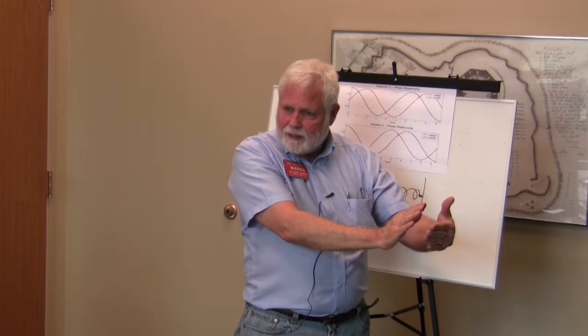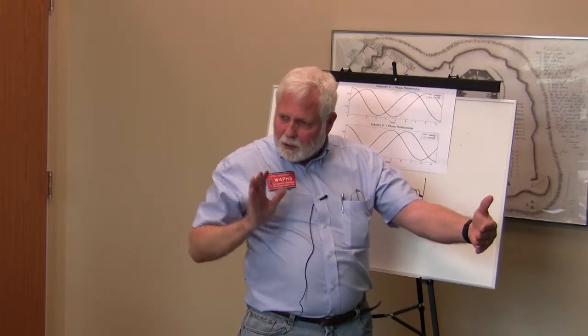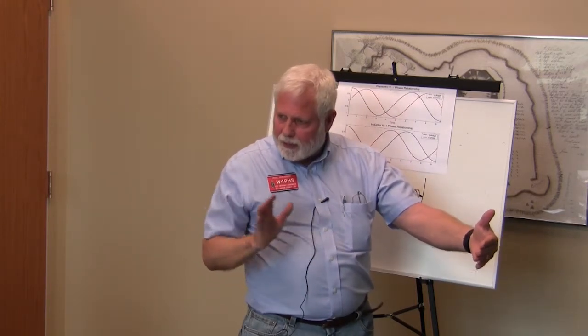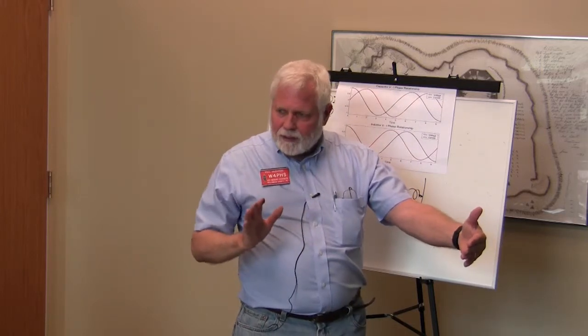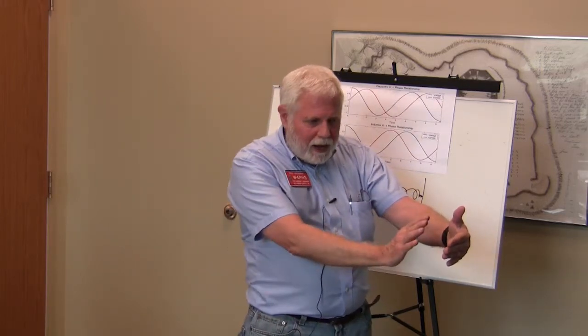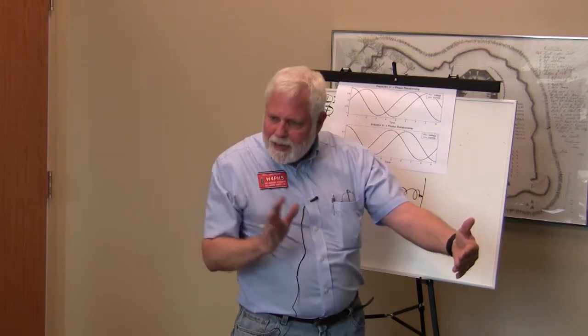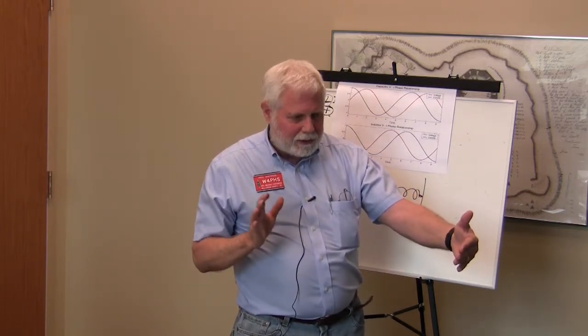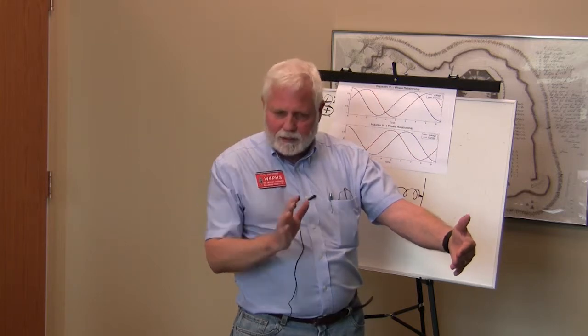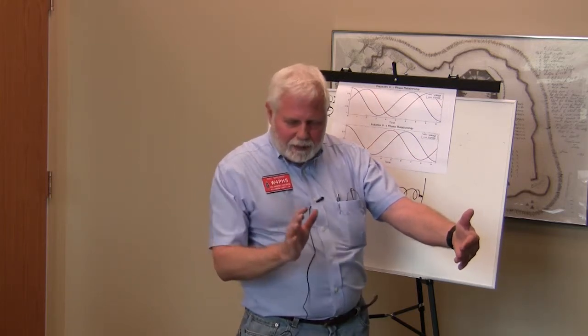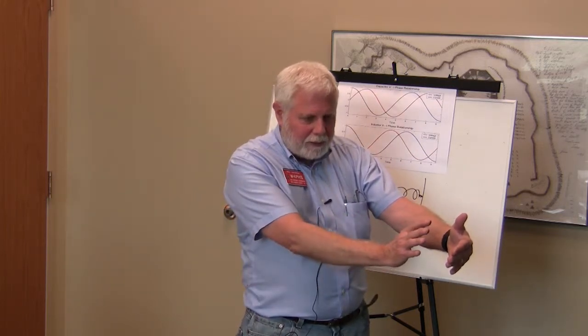You see what I'm saying here? Think about a spring. You start pushing it, but the force is very low at the beginning when it's uncompressed, and the force gradually gets higher as you compress the spring. But the speed immediately goes up as soon as I start pressing, because it's not resisting me. As soon as I start moving, it starts moving. But its speed gradually slows down as I compress it.